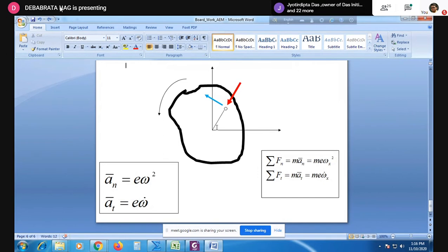If by chance the angular speed of rotation of the body happens to be equal to the natural frequency of the body, then there will be mechanical resonance, an enormous amount of vibration may take place, and there can be extreme phenomena like seizure of the shaft within the bearing. So the shaft will get completely stuck in the bearing.